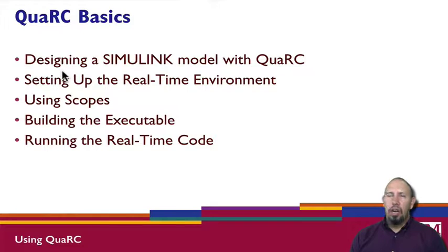So I'm going to cover the basics of QuaRC, which is an extension of Simulink. So we're going to talk about designing a Simulink model with QuaRC, setting up the real-time environment in QuaRC, using scopes, building the executable, and then running the real-time code.